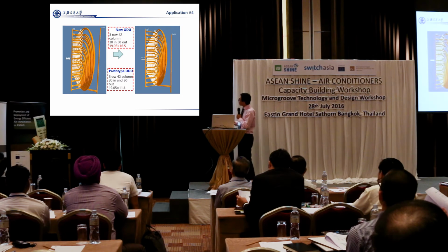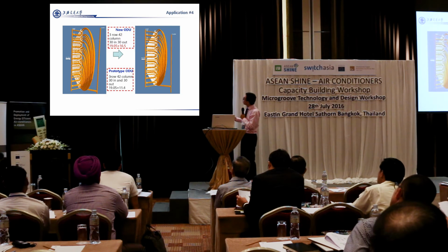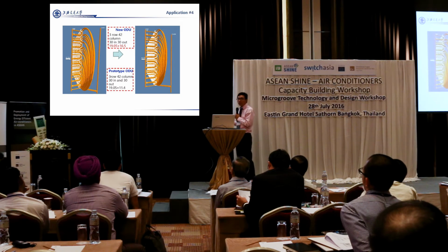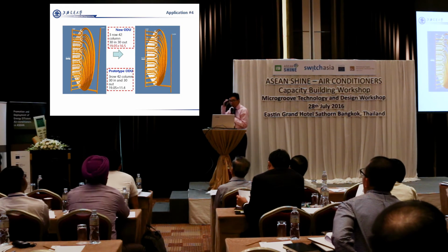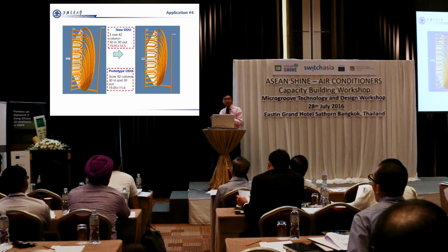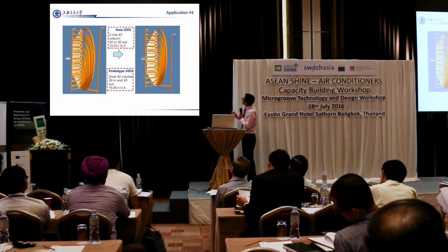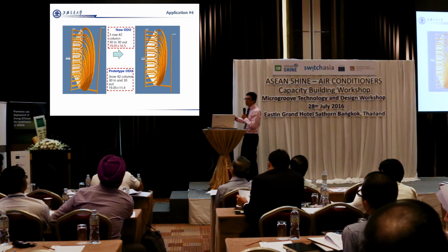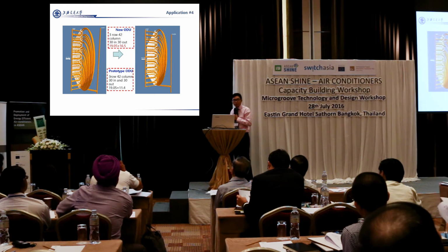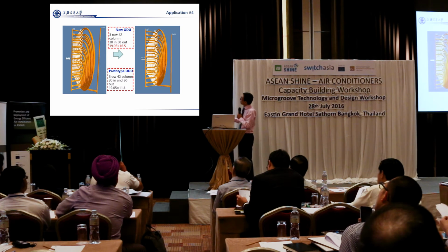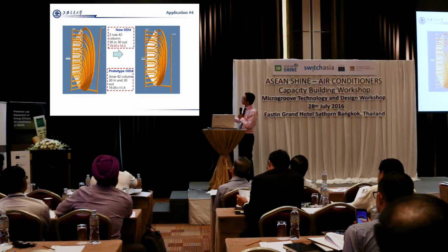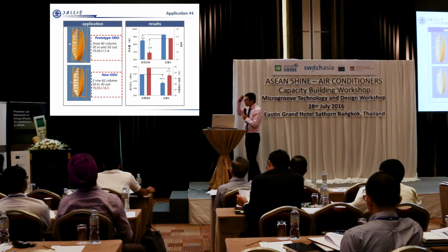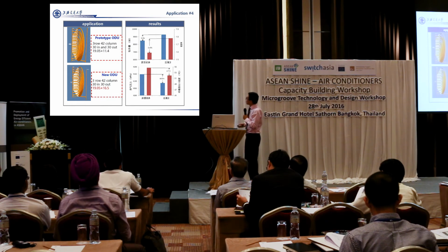At first we used this fin pattern to modify it and got this result. And we found that in some high ambient temperatures, like T3 working conditions, this machine does not work very well. So we suggested using a wider fin. And this is the result.